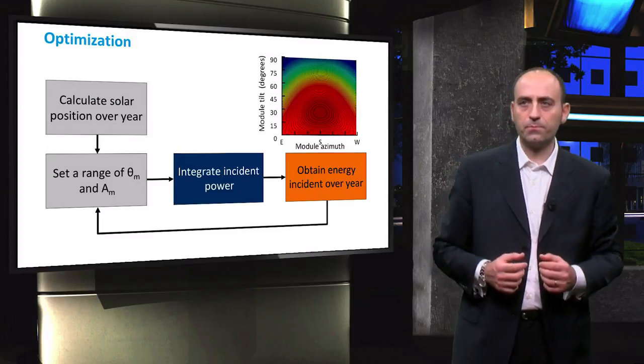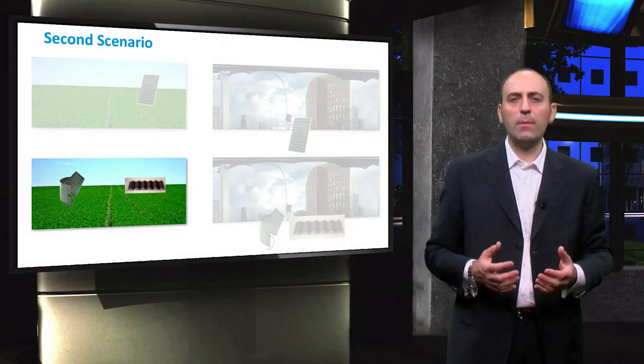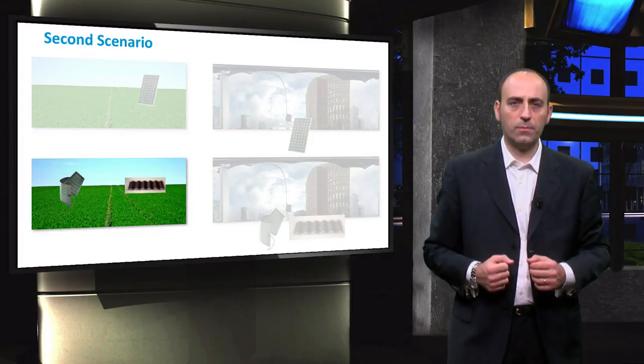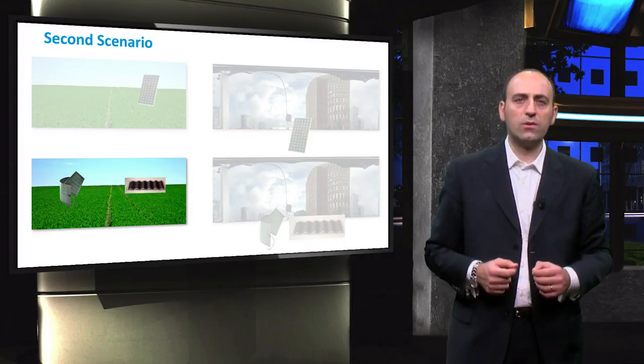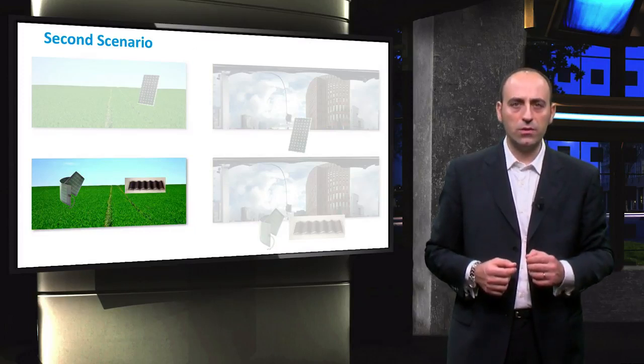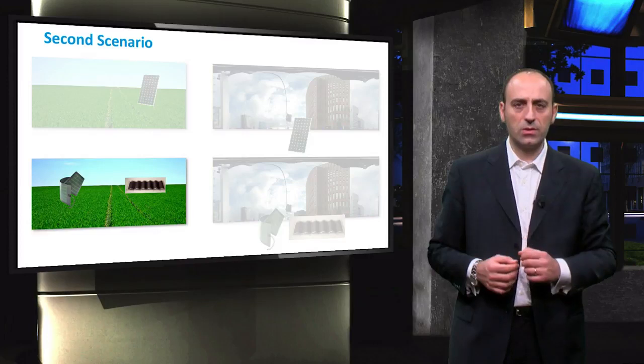But one major disadvantage of this method is that it cannot be used on custom-shaped or non-standard PV modules. This is because such PV modules might have non-homogeneous irradiance distribution on their surface due to their geometrical shape. Hence, it becomes quite difficult to accurately simulate such irradiance distributions using this basic method. Hence, to solve this problem, a new type of irradiance model was developed. In the next scenario, where free horizon and the non-standard PV modules are considered, this flexible irradiance model is discussed.